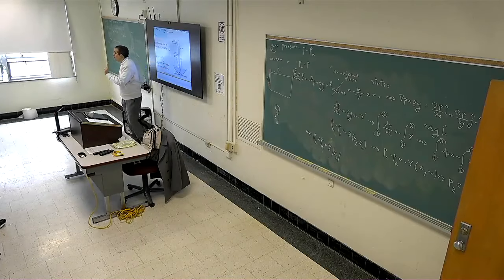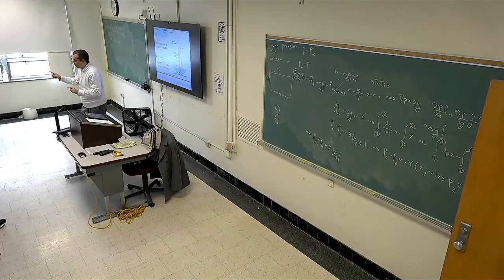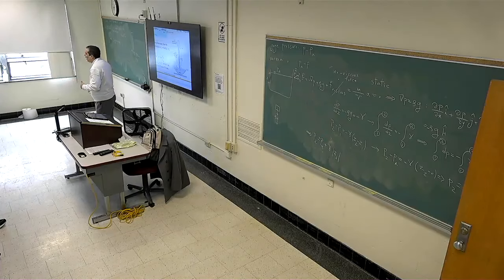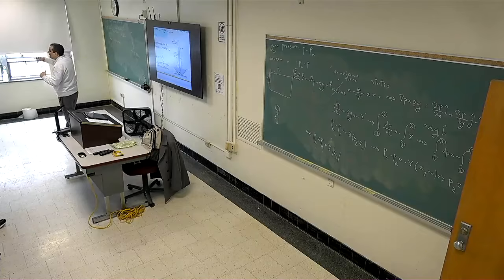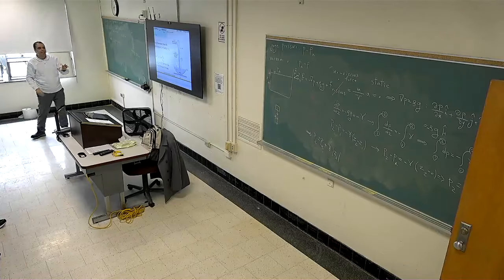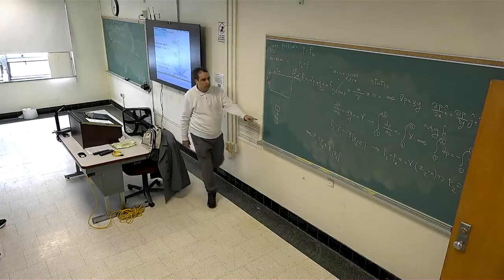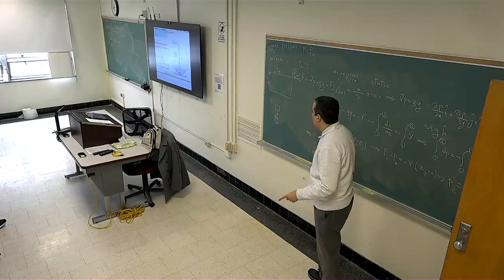So why do we use mercury, not water, in that? Because mercury has a high gamma and doesn't move a lot with the pressure changes. If we have water, we need a pipe of a few meters. But when we use mercury, we need a pipe of a few centimeters. Because when your gamma is high, your displacement is lower, for the same amount of delta P.